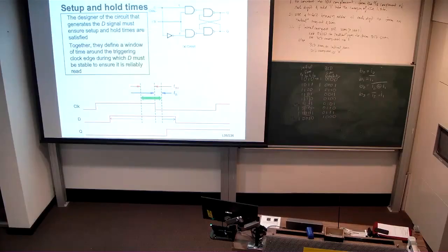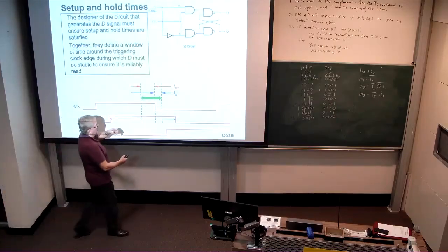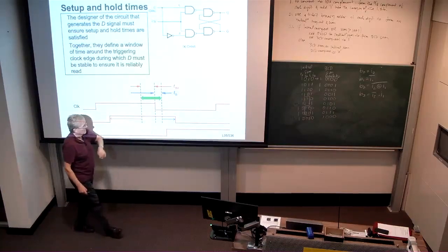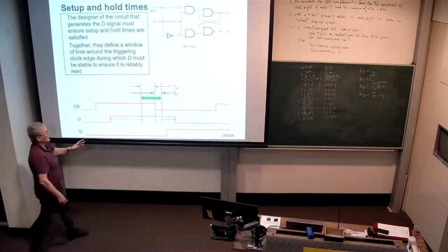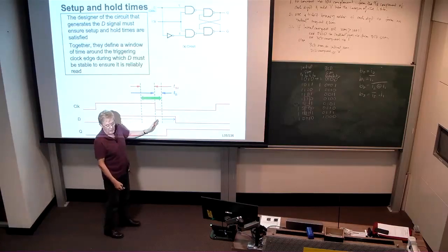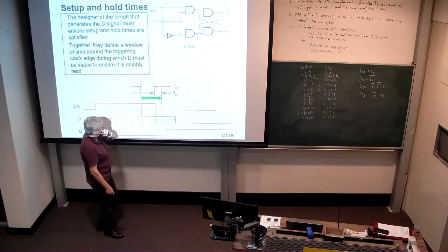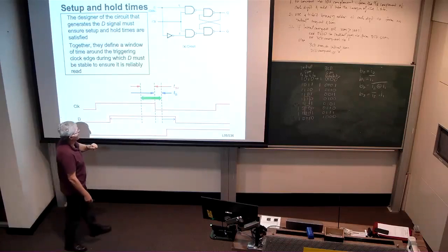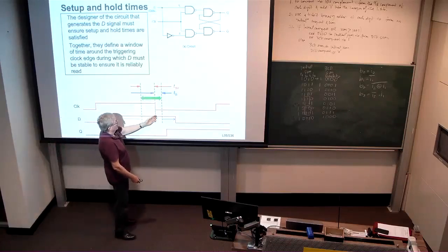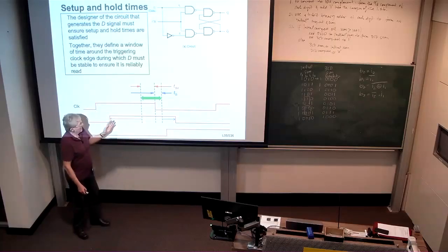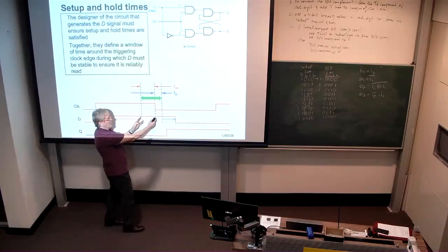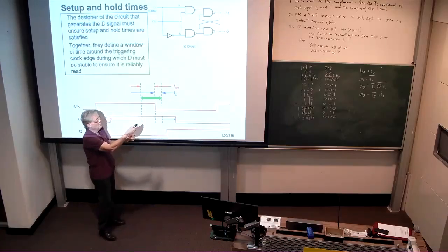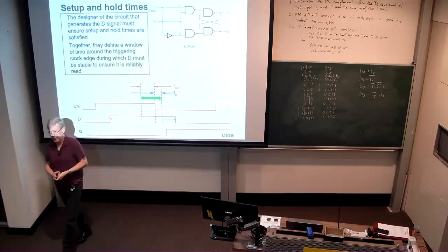So we've talked about the clock to Q propagation delay. Now I want to focus a little bit more on the setup time and hold time. Here, with respect to a D-type flip-flop, we're going to look at what happens when the clock goes low on that gated D latch. So when the clock goes low, there's a period of time prior to the clock going low whereby the signal has to remain constant, otherwise it will not be seen on the output side of the